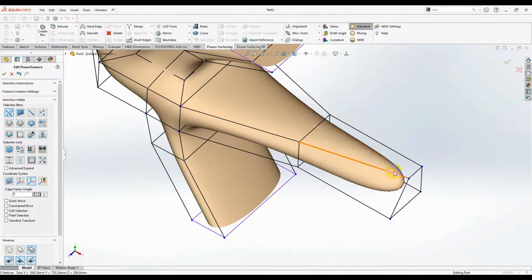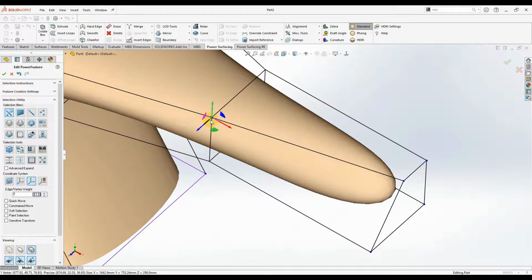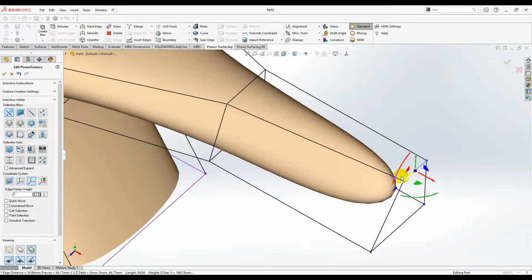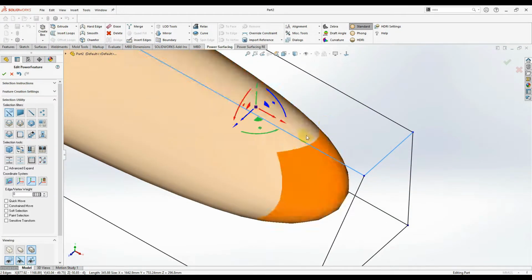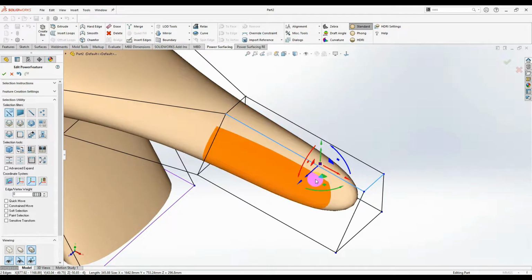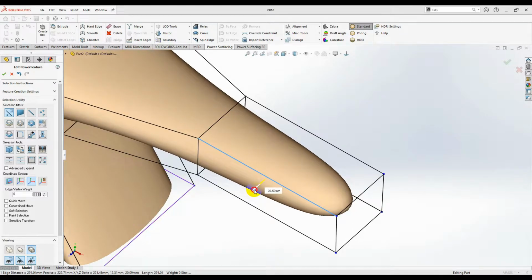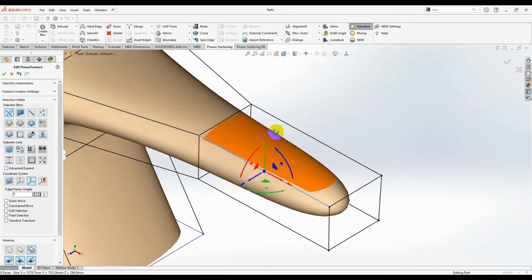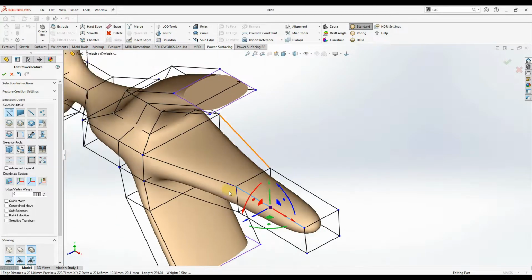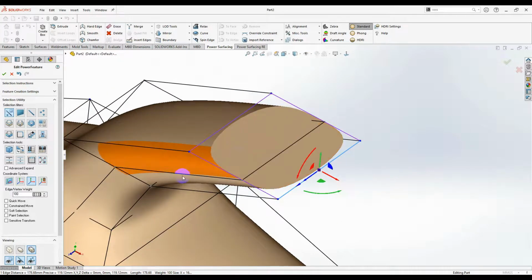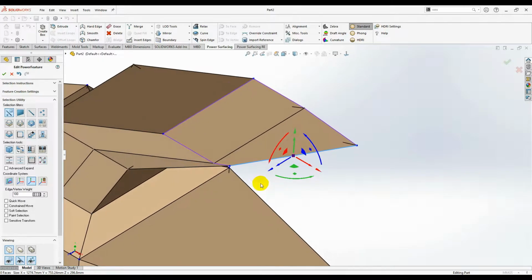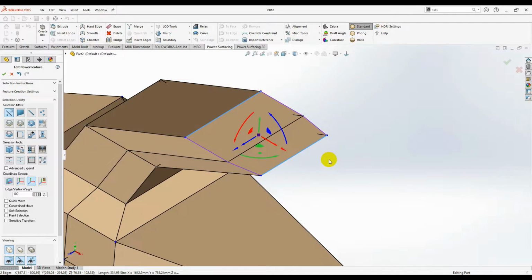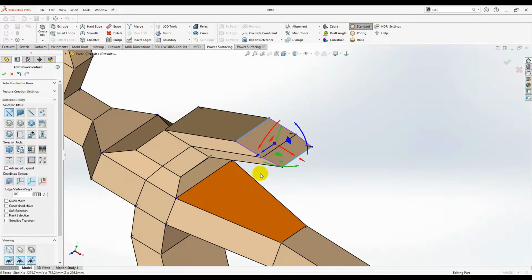something like this, I can select both and I can align them perpendicular, so it gives you a perpendicular angle, and then I can just move it to get the 90 degrees. Okay, now you have also the parallel. Let's say if I just move this a little like that, and I need both of these lines parallel, I'm gonna select line parallel, so it gets parallel with that.